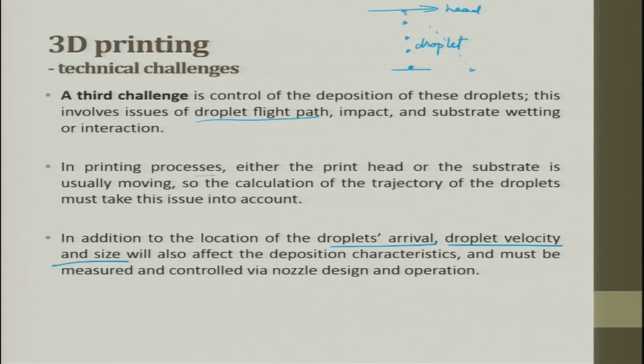At the exit they have a piezo crystal. The opening on the piezo crystal happens so fast and the droplets are formed and allowed to drop. If the droplet which is formed is too small, then in the flight movement, when the binder head is moving, this droplet will just ooze out and fly in the air. So, you have to be very careful. So, this is a huge challenge.